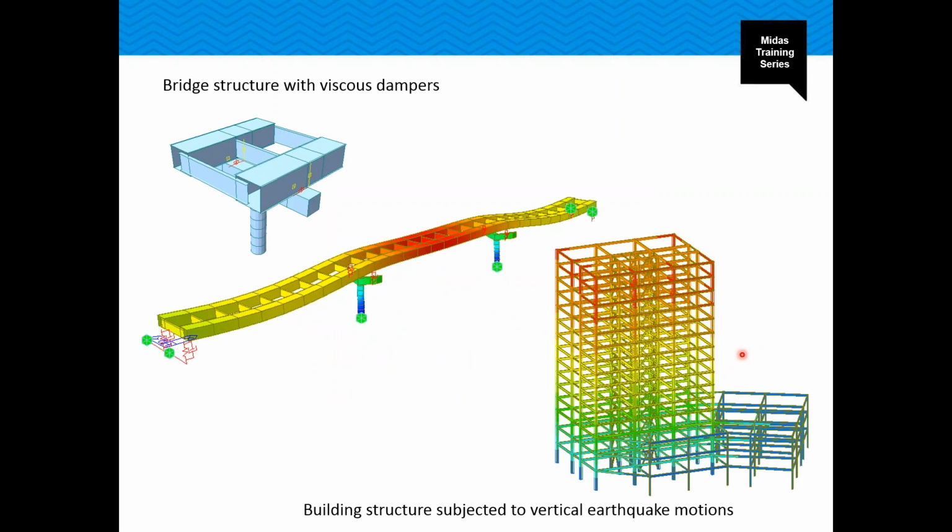In this bridge, viscous dampers are installed. The bridge will be deformed in a linear elastic range, and the dampers will undergo nonlinear behavior when subjected to an earthquake. This system can be solved by nonlinear modal time history analysis, which requires modal analysis. The number of modes of vibration of the damper is small compared to the response of the structure.